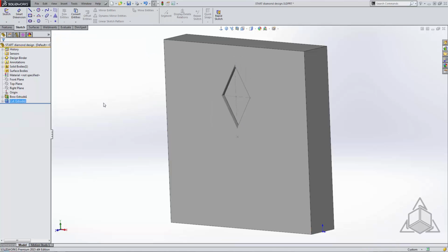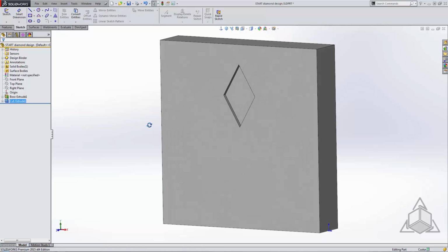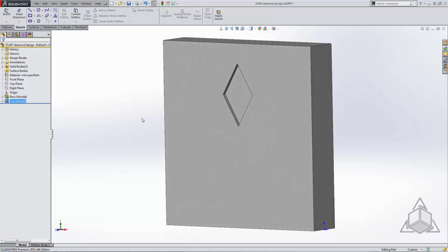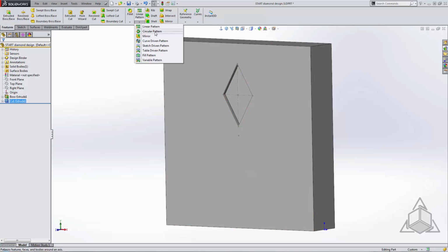Okay, simple cut. I'll hide the sketch. We can see that there. Actually, I'm going to show that sketch again because I'm going to use this sketch point, because I need to make a circular pattern of this using my circular pattern feature. But for a circular pattern, I need a cylindrical edge or a cylindrical face or a circular edge or an axis of rotation. I don't have that right now, so we need to create it. I was very careful to create this point not related to anything other than these two edges, remind you.